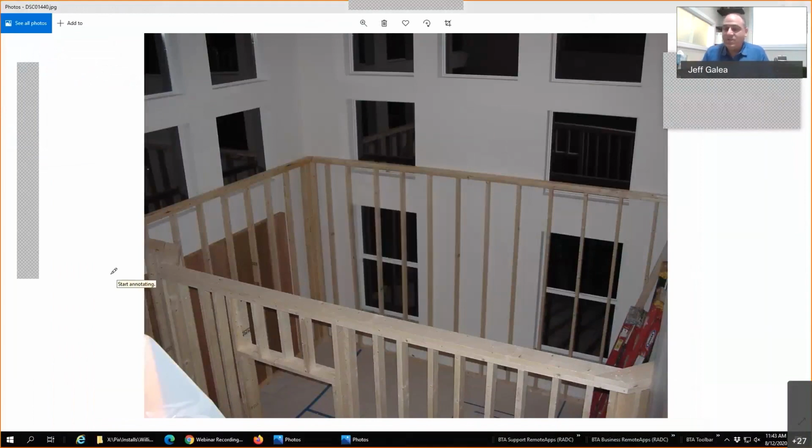so this is actually a picture that I took of my own theater when I was constructing it. This is a room within a room, 2x6 staggered studs. The top cap and the base that attaches to the floor are 2x6, and then we have 2x4s. You can see each one of these various things is staggered. When we put the floor in and the riser in the back, it did not touch the wall, so that the vibrations from the subwoofers would not transmit through the members of the stud cavities and whatnot. They're just decoupled.